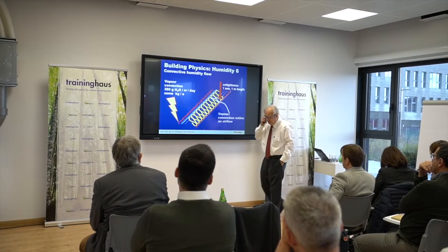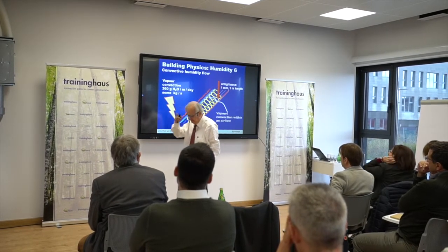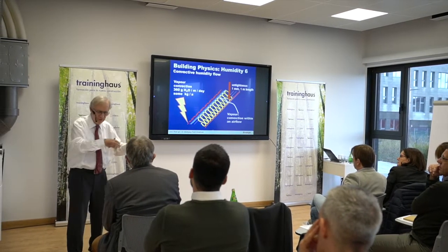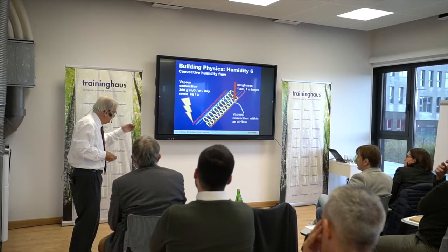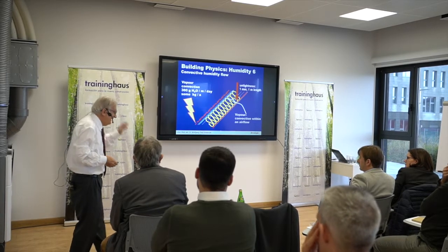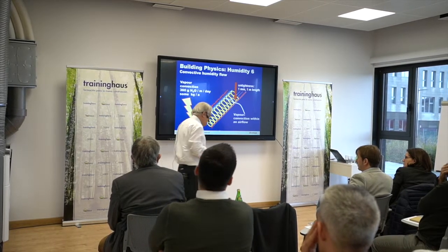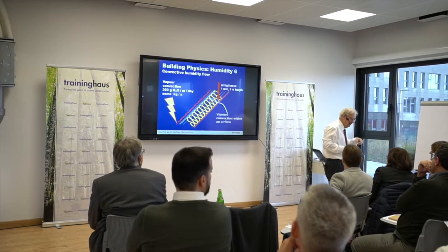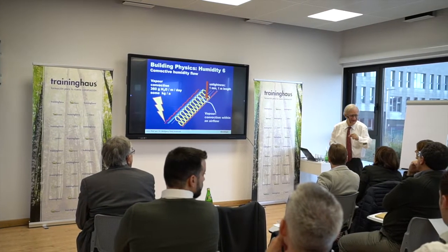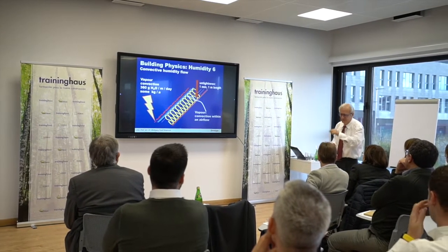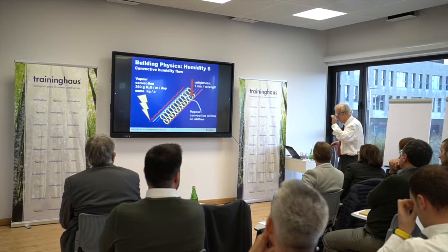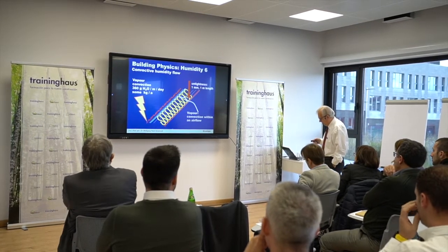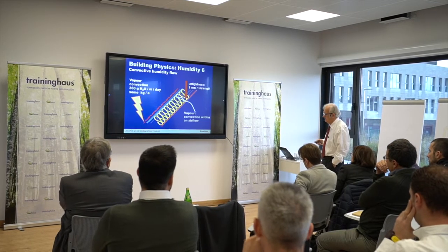I don't think I have a picture in here. In the other presentation yesterday, I had a picture showing this with a modern roof. Yeah, that if it's not airtight, you have this type of damage. So that's the most important slide here. That is the reason why in winter cold climates you have to build airtight, right? Because otherwise you almost immediately get these types of water humidity induced structural damage.